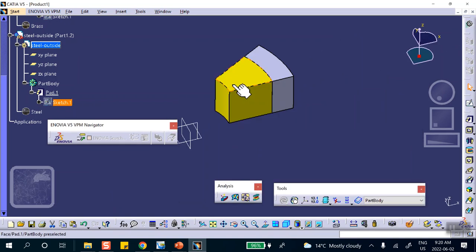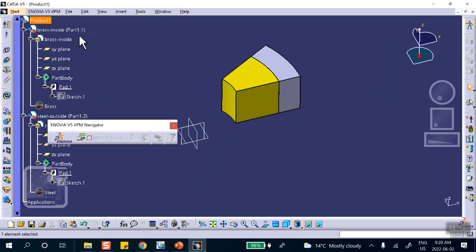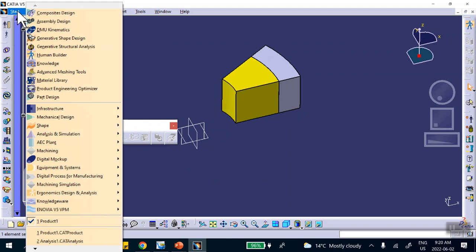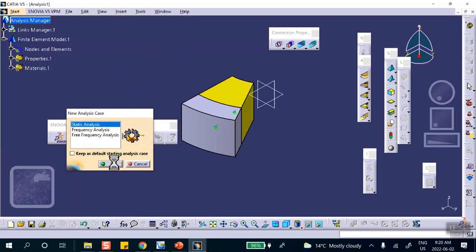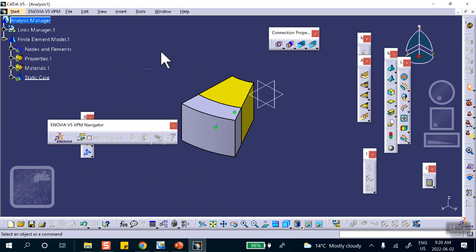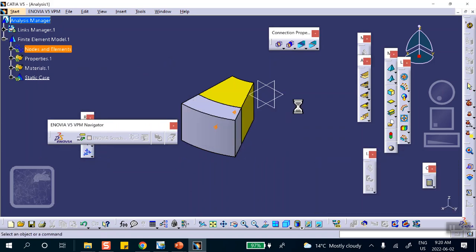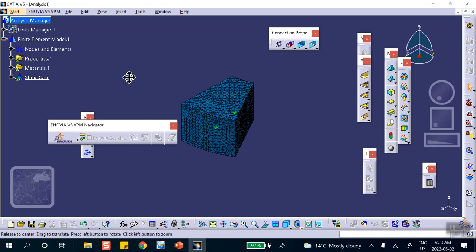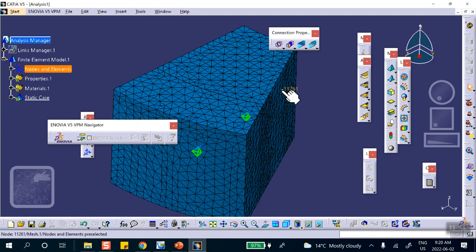Excellent. Now, we go to the analysis. Now, when I go and check my video, I will see whether those icons were on or not, because I have a feeling that they were off, whatever reason. CATIA meshes both of these, okay? And if you want to look at the mesh, right-click Mesh Visualization. There we are, okay? Now, I know that there is a severe discontinuity at the seam. See that at the seam?